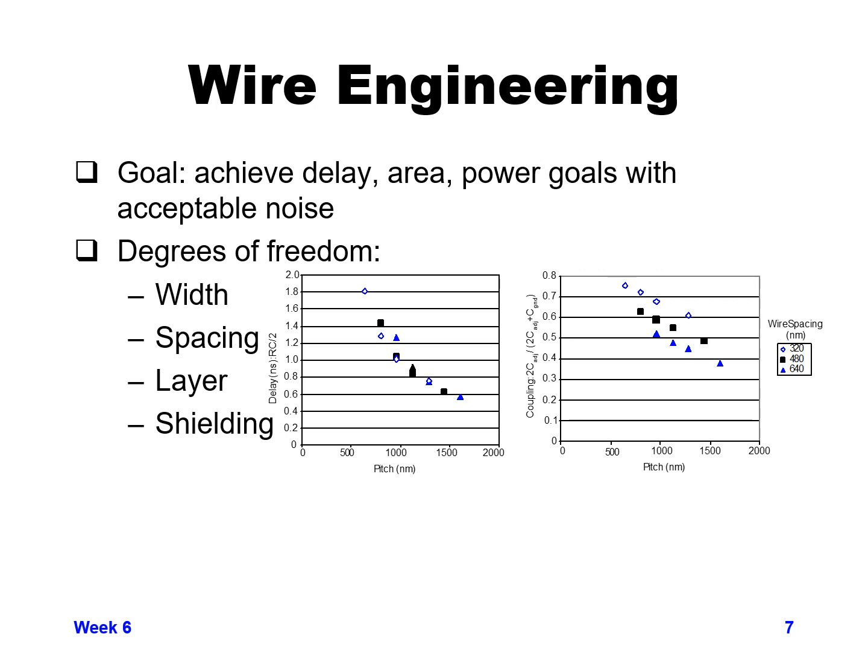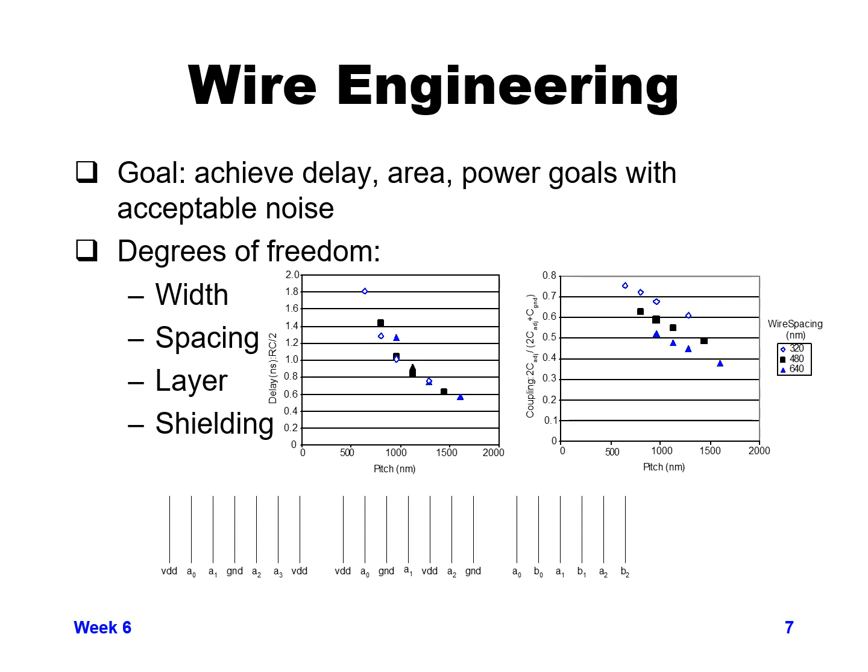Shielding can definitely help. So rather than putting two switching wires right next to each other, you can put a wire next to the track next to either VCC or ground, and you'll now have a constant voltage next to it, so you won't have any coupling going in the opposite direction when you're trying to switch. So shielding can help prevent or reduce your noise. Down below here we can see an example of how shielding can be used.